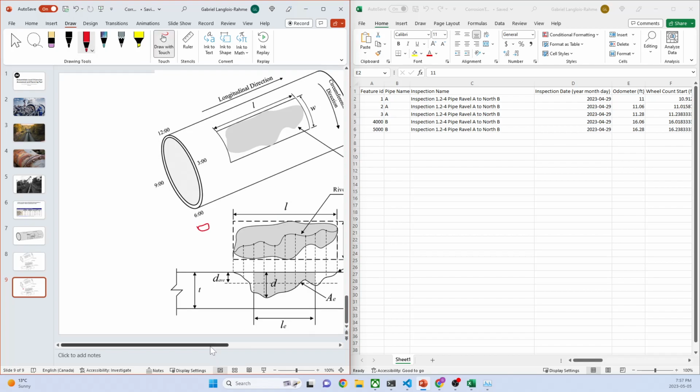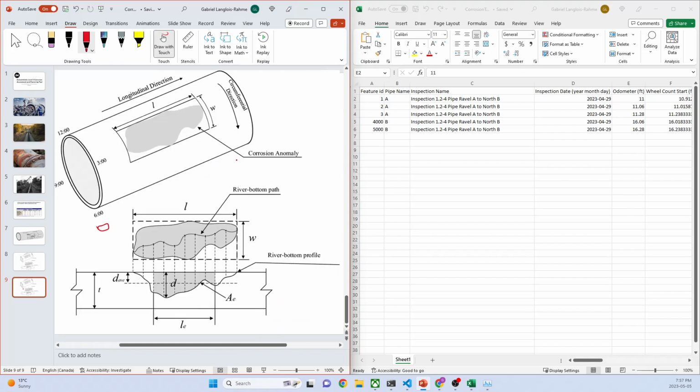And then you run it across your pipe, and it goes up to, let's say, 100. Make it really simple. And it detects corrosion at some location. Let's call it 50. 50 is your odometer. So essentially a spatial location on where it ran.